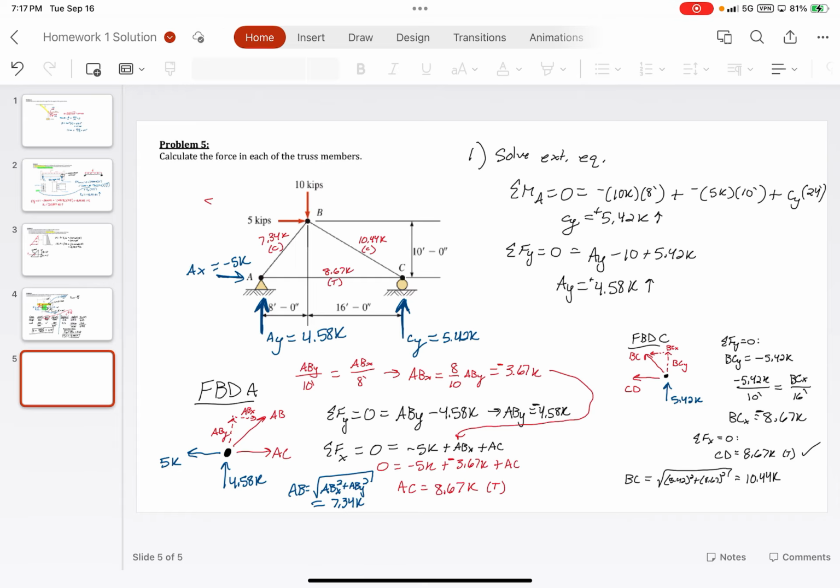Right. So here's a nice little trick. 5 kips going down that way, 5 kips going down that way. They both have the same moment contribution, which means all the force is going to be concentrated at G. It's not what you're showing here. So make sure to clearly not multiply when you're doing sum of the forces in Y or sum of the forces in X. There should be no multiplication going on. So it should be just -5 plus GY plus AY minus 5 again.